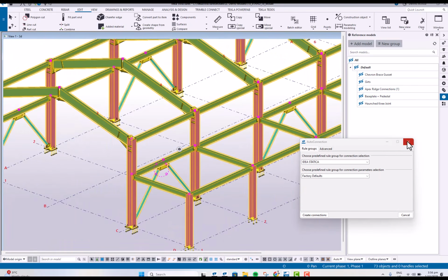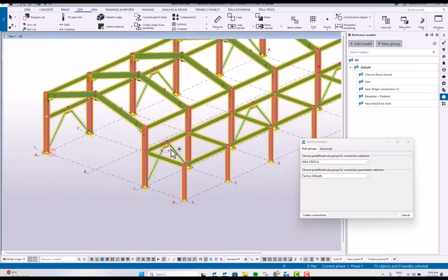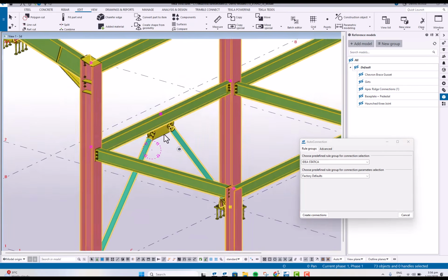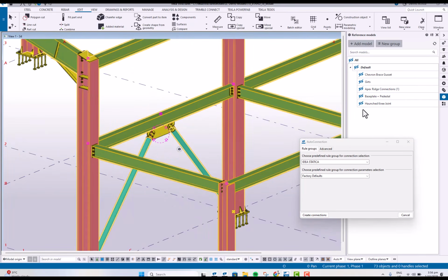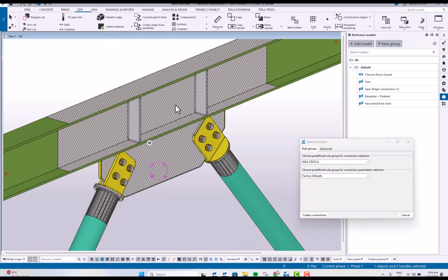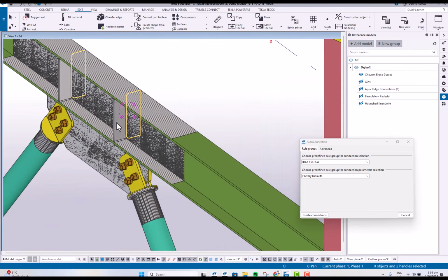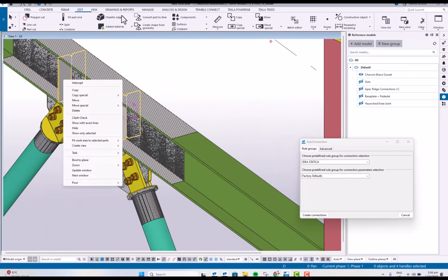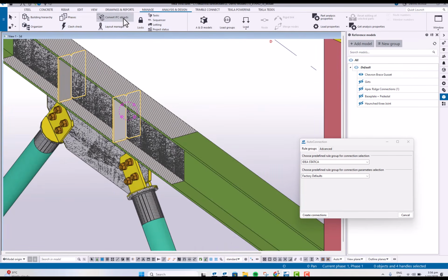Also, going back to what Engineer Jean mentioned, if I have this chevron gusset plate like this, look at this. It is also possible to select this element, this element, this element, and then I can simply convert to IFC object.